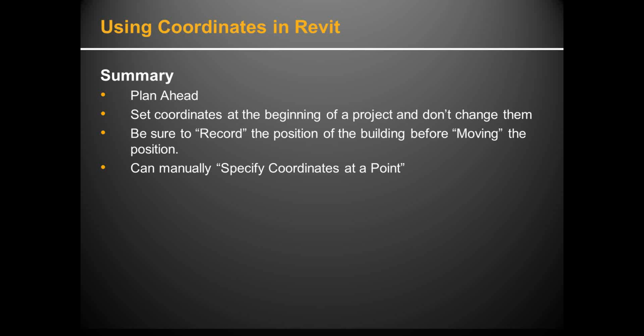All right, Tony. Just had this slide up here for a little while, but summary, number one, plan ahead. And along with that, set the coordinates at the beginning of the project, and then don't change them. If you can help it at all, set at the beginning, and don't change the coordinates after the project is started. Brian, would you add anything else? I put on there, be sure to record the position. That was just one of the pitfalls before moving the position and when you're in that dialog box.